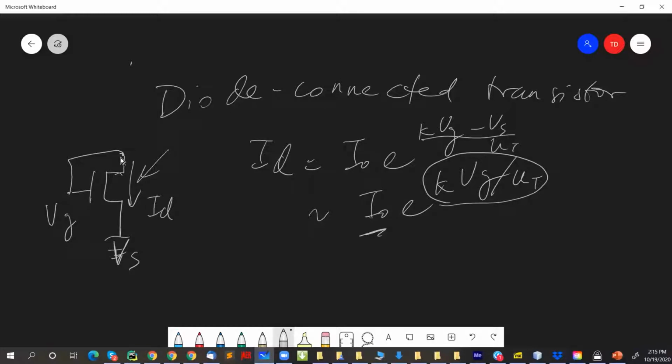Okay, and so the transistor operating in saturation is going to be true whether you're in subthreshold or above threshold. It's useful to know that you have these two regions of operation of the transistor: subthreshold, where the gate voltage is less than the threshold, and the above threshold regime, where the gate is above the threshold. But in both regimes, you have the linear and saturation regions, right? There, what you look at is the current as a function of the drain voltage. If you do this for subthreshold, then you get some increasing current with VD, and then at some point you saturate. This is usually around 100 millivolts, okay?